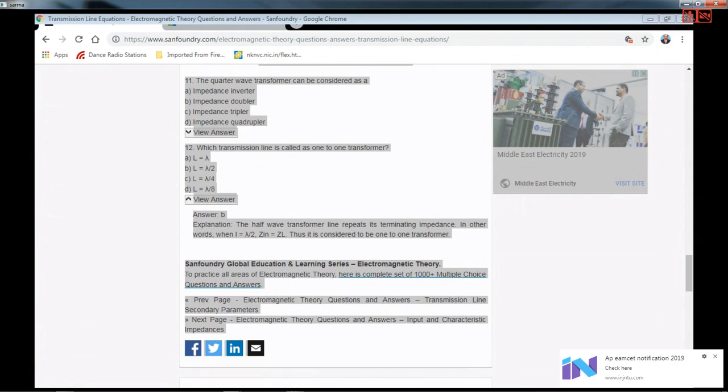So, forward wave will have different voltages and phases. Similarly, reverse wave also will have different voltages and phases in a general case. So, the ratio is going to get changed. So, this ratio is also difficult to measure. In good olden times, there was no way to measure this particular quantity, because the voltage and current on a transmission line is finally a standing wave, a mix of these two things. So, dividing the forward wave and reverse wave and taking the amplitudes of the forward wave and reverse wave to get the ratio of them was a difficult thing in good olden days.